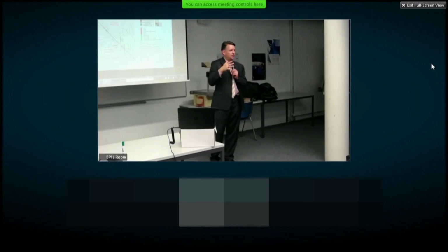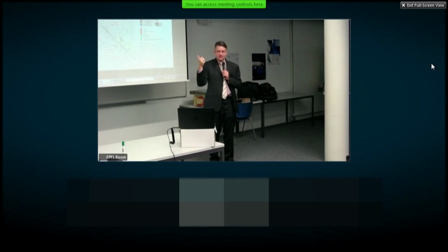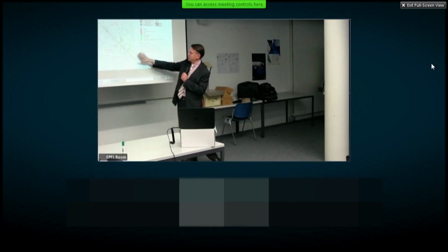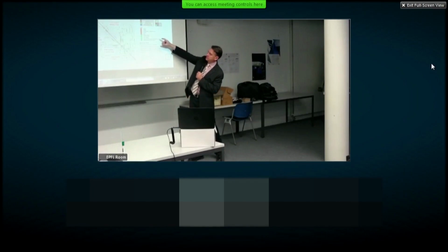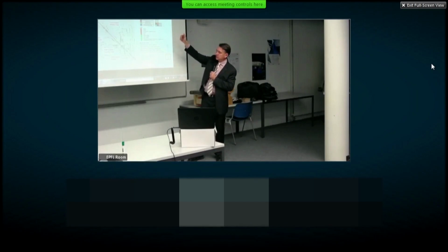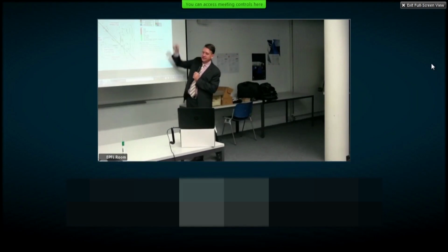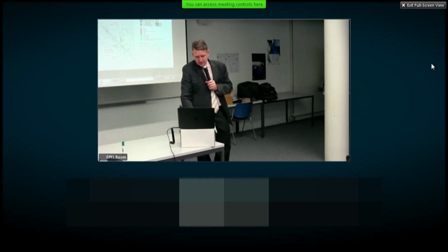So the machine has been decomposed into 84 really subsystems, because you have a lot more than 84 parts. But at this level of abstraction of 84 by 84, we have a total of 572 physical connections, 45 mass flows, 167 energy flows, and 165 information flows. And there's a little more detail here in terms of the types of flows. So in red, we have mass flows: paper, toner, air, ozone, and dirt, right? Because you've got to keep dirt out of the printing engine, which is shown here in the middle. Let me just show this.